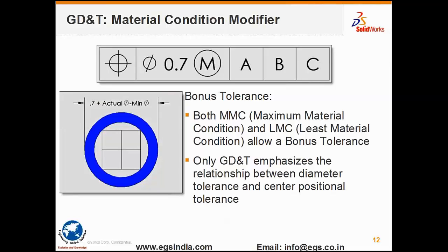Now, normally with the plus or minus tolerancing, you can see on the left side the square tolerance zone sitting there with a circle around it being the MMC virtual condition boundary schematic. Now, if you look at it further on, you will see that as you move away from MMC to LMC, the tolerance grows. In other words, at MMC it is 57%, beyond MMC it is much larger, even up to 100% tolerancing. So the myth that GD&T is more expensive as compared to plus or minus tolerancing is clearly negated with this approach in GD&T.